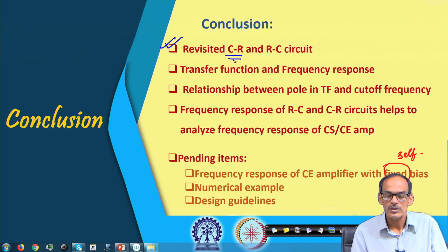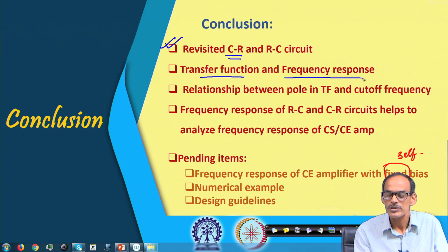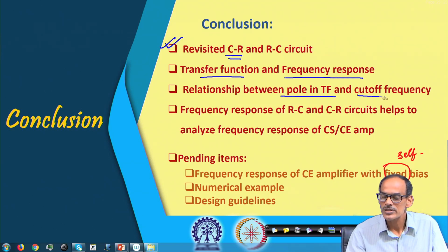With these two examples independently, we have seen the transfer function in the Laplace domain, the S domain, and the frequency response while changing the frequency along the omega line, and that they are definitely related. The important thing is that the pole in the transfer function in the Laplace domain and the cutoff frequency in the frequency response are directly related.